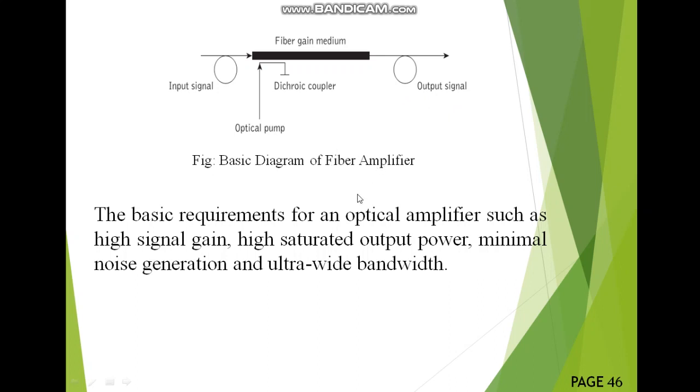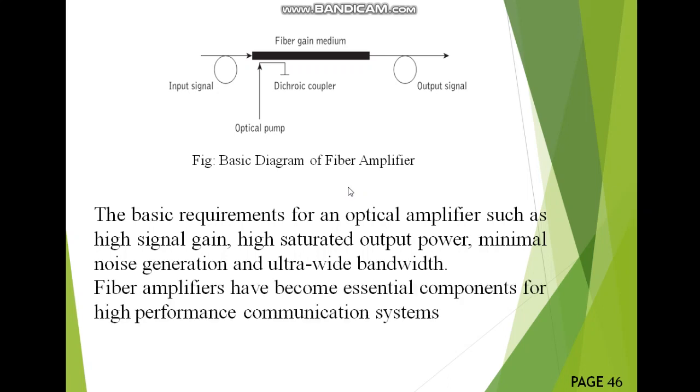In all fiber amplifier devices, the spectral bandwidth and central wavelengths are largely defined by the atomic structure. The gain medium normally comprises a length of single mode fiber connected to a coupler which provides low insertion loss at both signal and pump wavelengths. Excitation occurs through optical pumping.